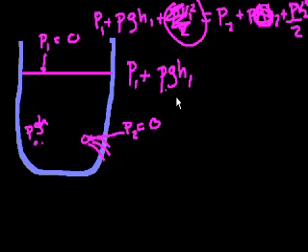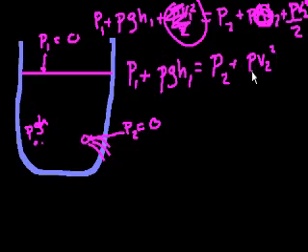This was kind of the potential energy term when we derived Bernoulli's equation, and that equals the output pressure, or the pressure at the output of the hole, at the right side of the hole, plus the kinetic energy, rho V2 squared over 2. The kinetic energy term, because this actually doesn't add up completely to kinetic energy because we manipulated it. And I just wanted to really make the point that this is definitely 0.